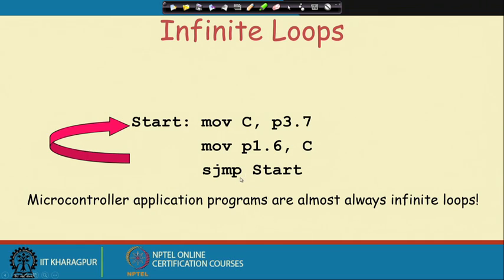Actually, many microcontroller applications are embedded system applications, like a temperature monitoring system. It controls the temperature of a room. That program will continually sense the temperature values and accordingly control the heater or the cooler. So, that program never ends. It continually looks at the temperature values and does the control. If you look at this type of program, you will see that at the end the program branches back to some infinite loop, and that way it continues.